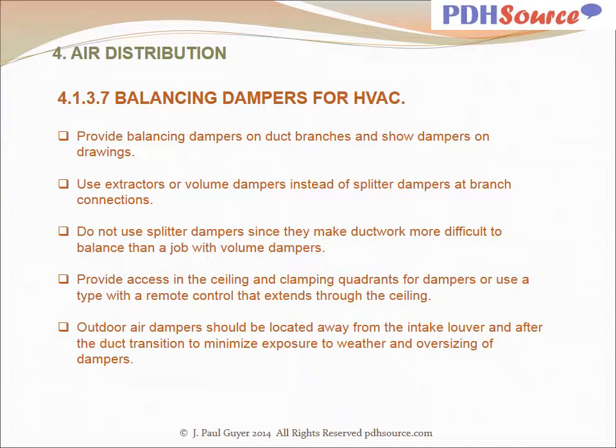Avoid using balancing dampers for industrial ventilation systems. Design industrial ventilation ductwork so that the system will function properly without balancing dampers. Do not use balancing dampers when designing a VAV, variable air volume system. A VAV system with ductwork designed using the static regain method and properly sized VAV terminal units is inherently self-balancing.